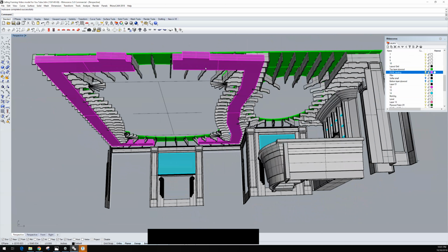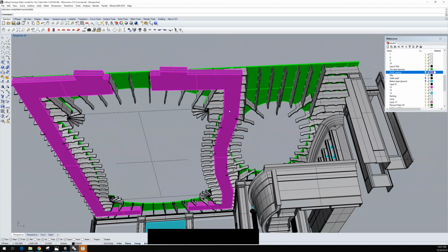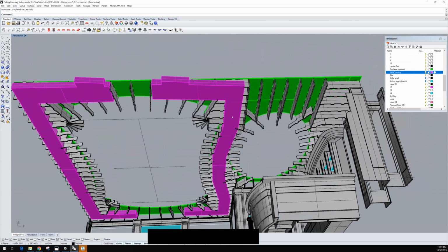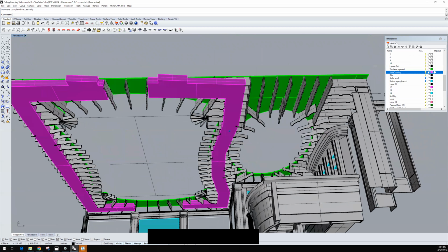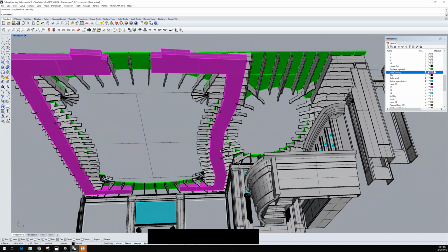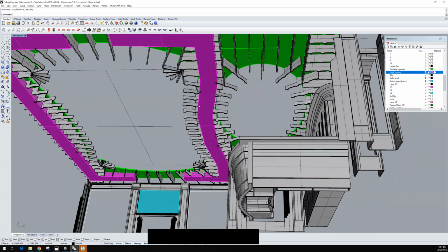So this ducting, we had the HVAC calculations generated, and we came up with a size of ducting that needed to travel through here. I believe it was 13 or 14 inches in width by 4 inches in height to get the volume that we needed to travel through here. So what we did is we created that model, subtracted from this grid, to make it travel down between the oval and this side over here. We had to have a little kink in it.